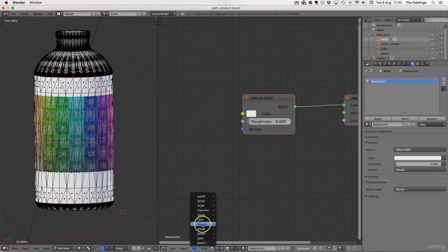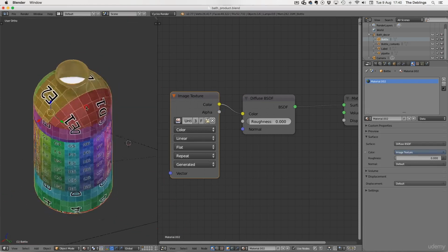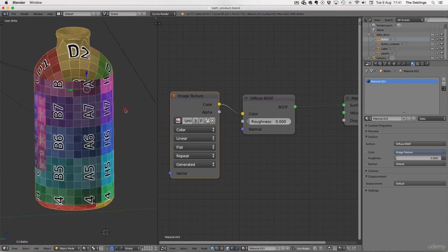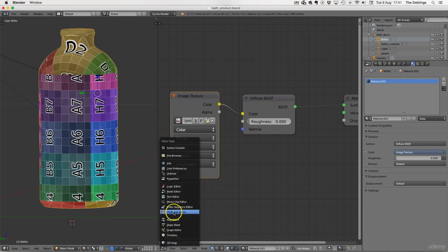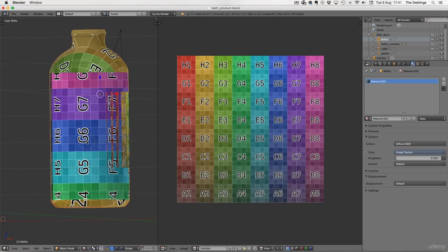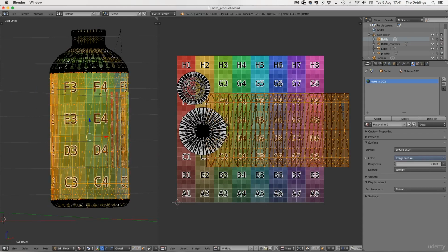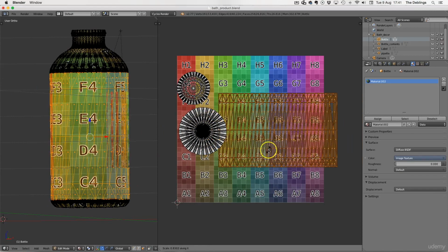Sort the nodes again for this second shape and resize your islands to have the correct proportion. So something that is square on the UV map should look square on your 3D view. So manipulate the 2D UV map in order to make that happen. Once you've done this for all your shapes, your UV maps are now ready to export, and that will provide you with a template for your designs.